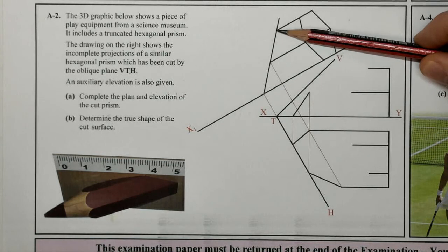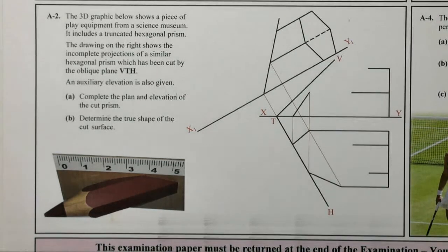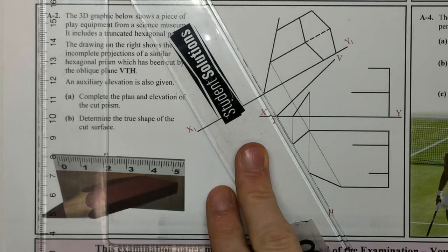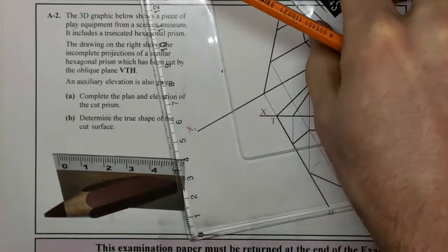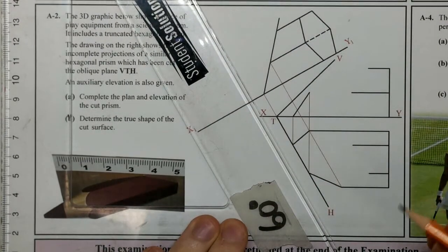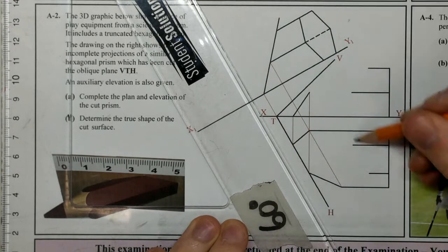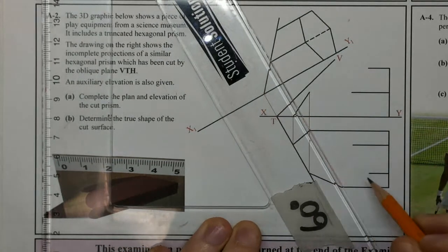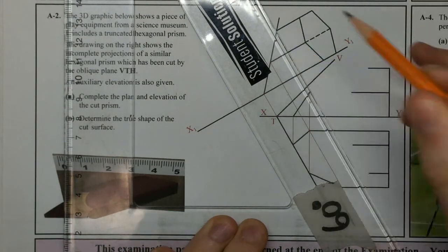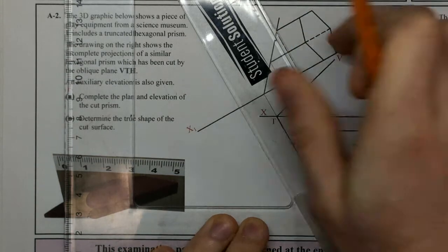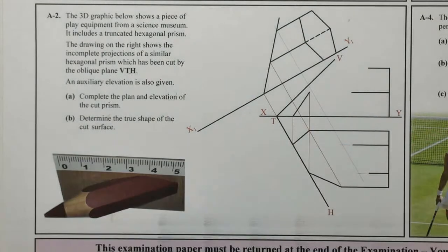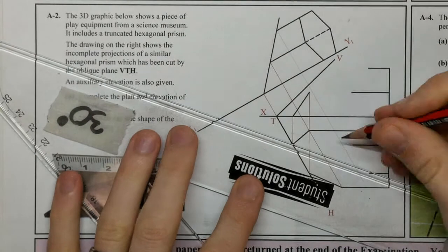So here is an edge view of that oblique plane. So that is where it has cut all those edges. So what we're going to do, see, is this a nice 6-degree angle? It is brilliant. So what we can do is we're going to project back onto the edges of the plane. So that's been projected back for the base, for the midsection, and here we're projecting back to the top edges, and extend those across. Okay, so that will allow us to draw in those edges.